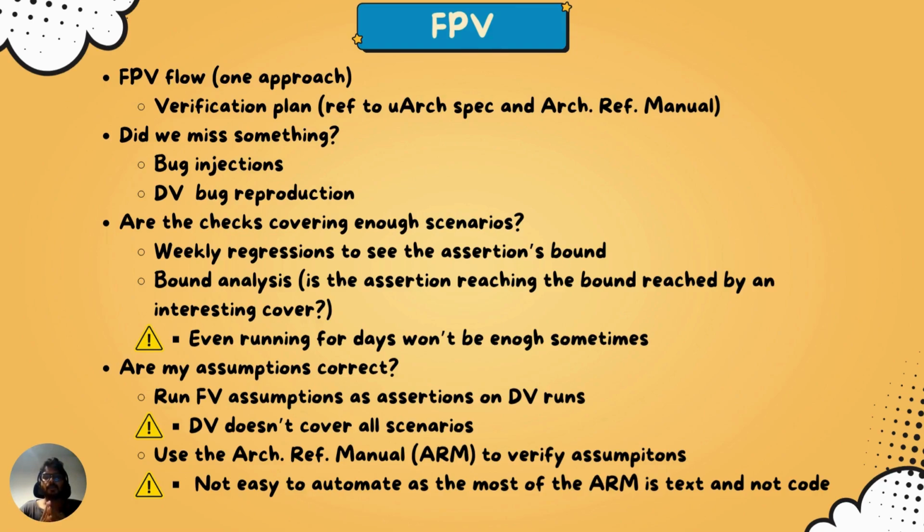You want to make sure that formal doesn't take any kind of crazy input which is not at all functionally possible, giving you a lot of false failures, taking a lot of your time. So you can apply constraints which make the input or the external world behave in a sensible way for the design. Now that said, let's go into the formal verification flow, or one possible flow.